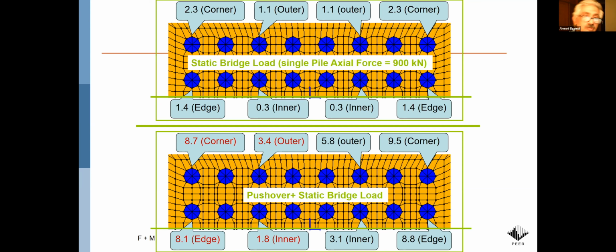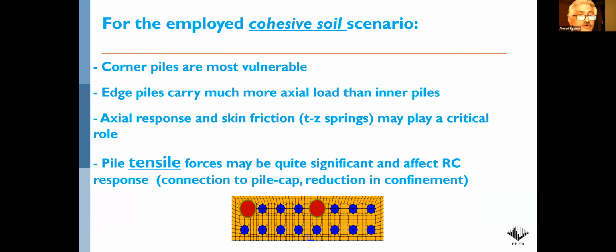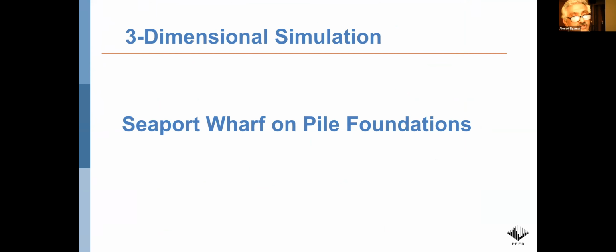And it was an opportunity for us to see that in addition to our interest in shear loading and the dominance of shear waves as the earthquake waves arrive close to ground surface, there are a lot of other characteristics happening in 3D and all kinds of loads on the ground that necessitate a much closer look at 3-dimensional response and models that reproduce this 3-dimensional response.